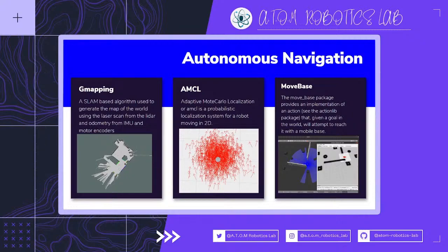For planning there are two types of planners, global planner and local planner. The global planner creates the shortest path between the points that we have given. It mostly uses two types of algorithm, or you can implement your own: one is A star and the other is Dijkstra. The local planner works with the local cost map and develops a small path in which the bot would take its turn. The basic local planner we use in our project is the DWA planner. Krish, continue.